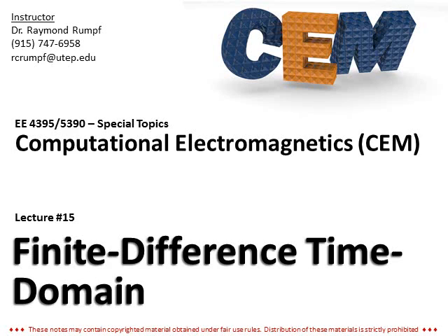So in finite difference frequency domain, we assembled a bunch of equations into a matrix equation, solved it with a backward division, and we had a snapshot of the fields at one frequency. Instead, we're going to solve Maxwell's equations in time, and this creates essentially a movie of the electromagnetic wave passing through your device, scattering, bouncing around, and you can watch that happen. It iterates in time, and you can watch your fields evolve. It's a great tool for learning, great tool for visualization, great tool for doing really, really large scale problems. When everything else fails, finite difference time domain usually doesn't.